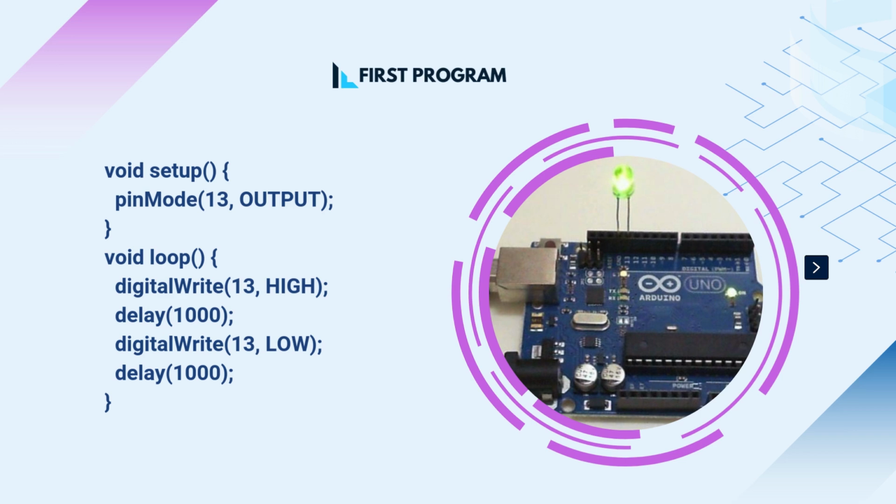Inside it, we write pinMode(13, OUTPUT). This tells the Arduino that pin 13 will be used to send signals out, not receive them. On most Arduino boards, pin 13 is connected to a built-in LED.